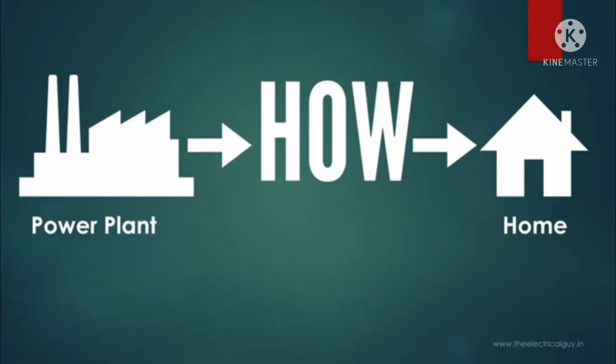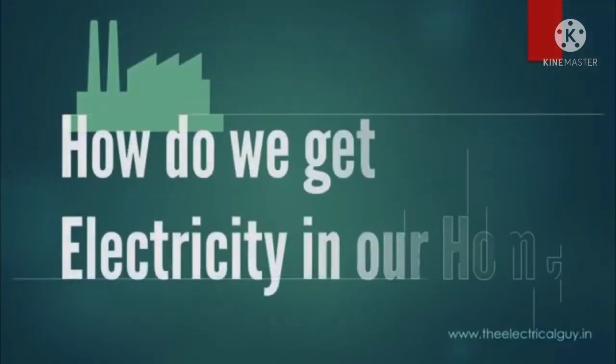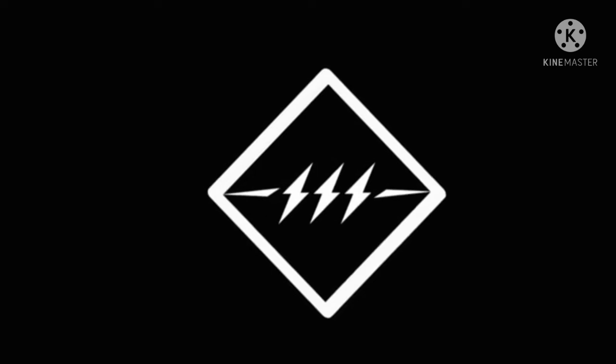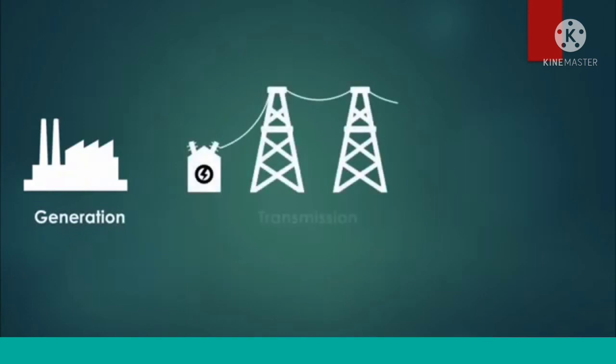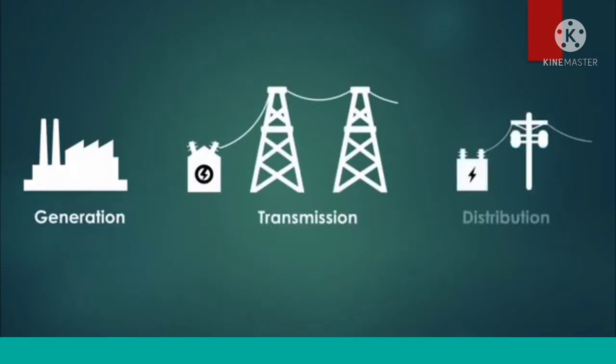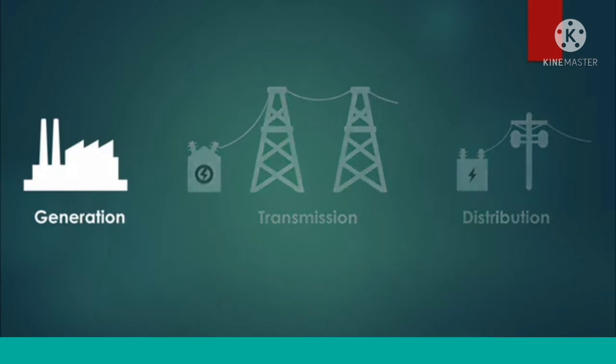To supply electric power to a house, either overhead wires or cables on poles, or underground cables are used. To connect the cables from poles to the meter in the house, first a fuse of high rating is connected in the live wire just before the meter. After this fuse and the electric meter, the main fuse is connected to the live wire, where the main switch is connected to the live and neutral wire.